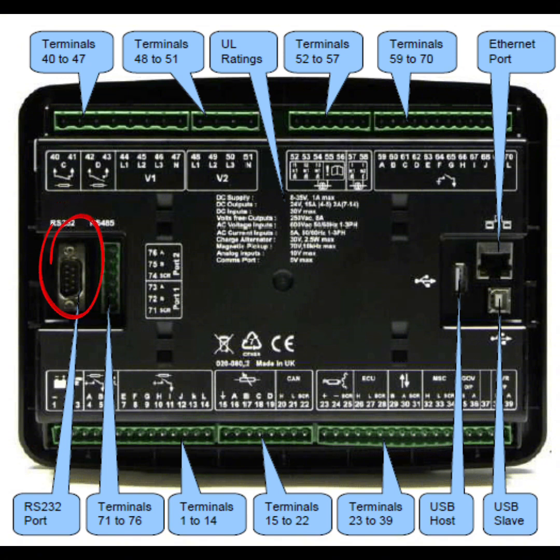Guys, this is the 2-port RS232. If you have any RS232 cable, you will connect it here. If you need data from RS232, you will connect your RS232 wire here, and near it is the RS485 jack. If you need a SCADA system, or need remote data from this controller, you will connect your RS485